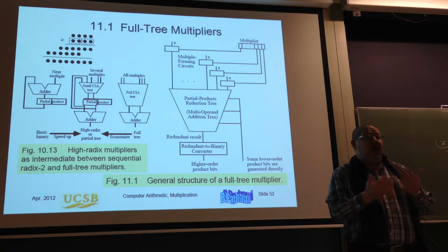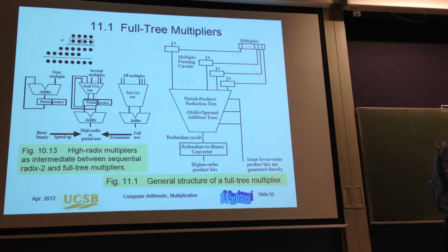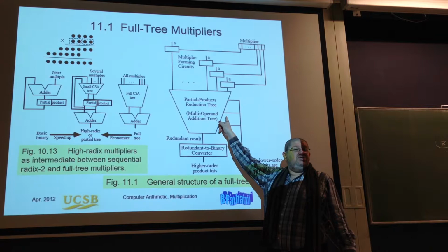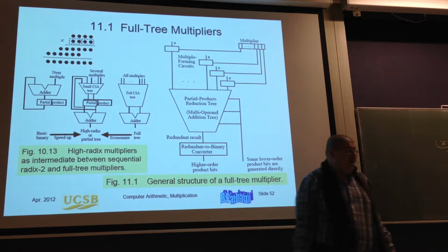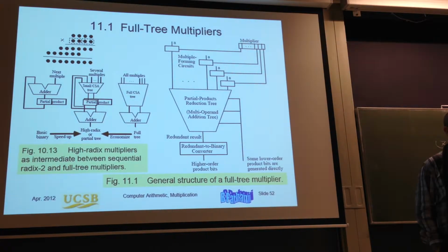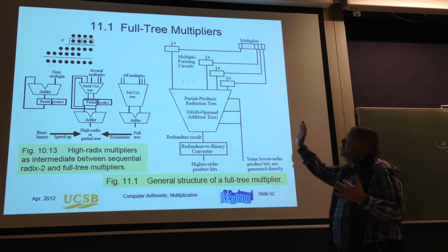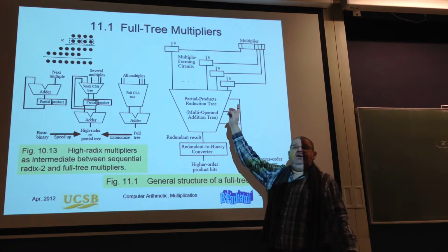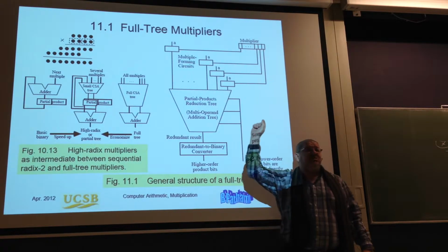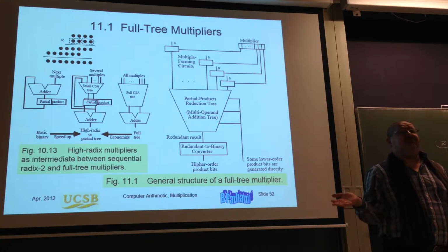In this way, I managed to get a processor where addition takes one cycle, and the rest of the multiplication takes another one. And because in this tree I can add another value most of the time without any problems, I can compute A times X plus B, which is the famous multiply and accumulate instruction, which all or most of the decent DSP processors have.